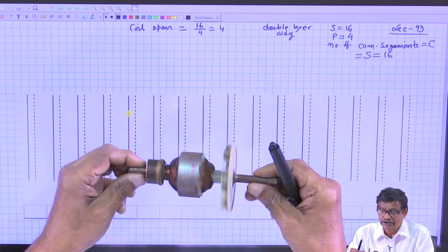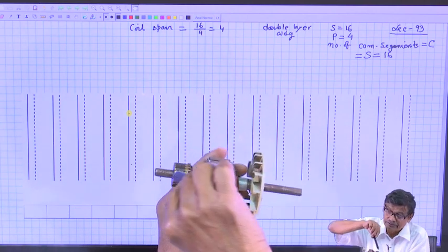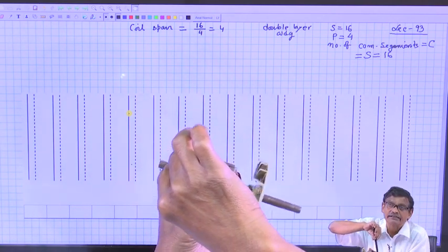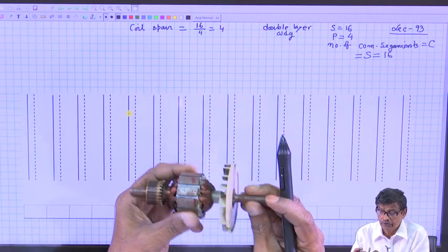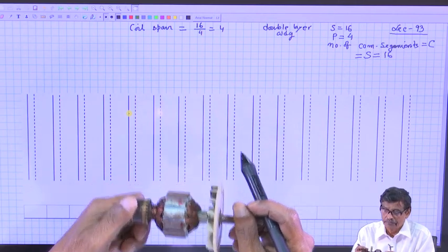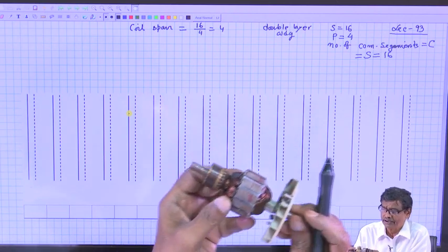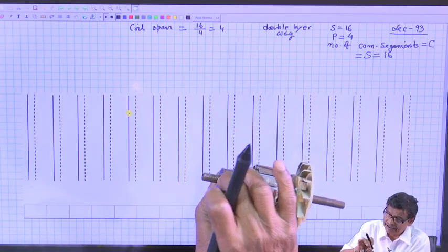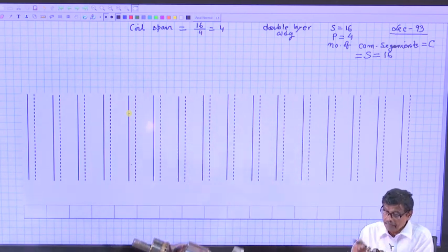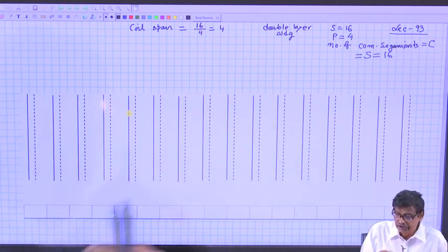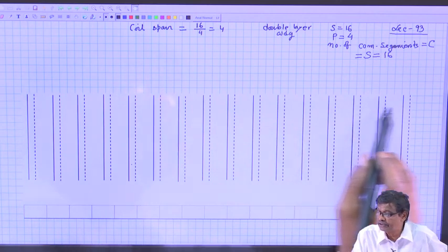Both armature and commutator segments will rotate, and brushes will be fixed in space and will touch different commutator segments, as we have discussed earlier. The commutator segments are nothing but a replica of the slots at a lesser diameter. The induced voltage depends on the coil sides, as flux will be present only in this portion.